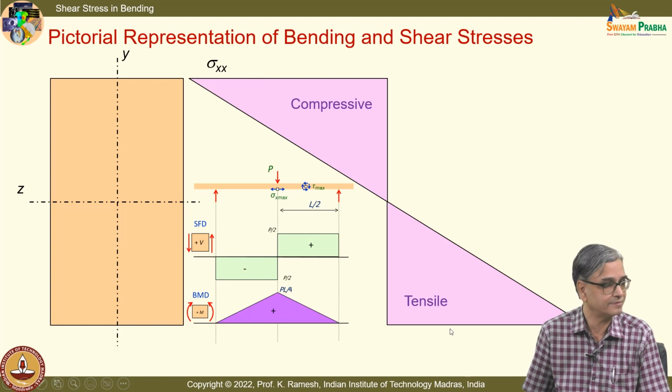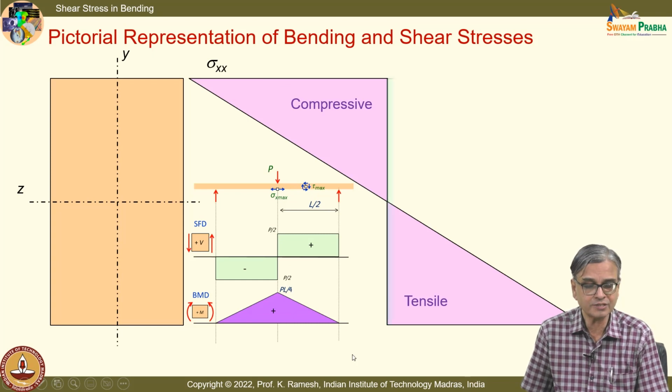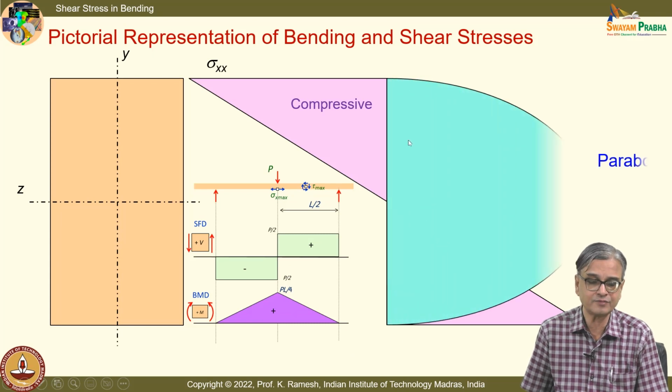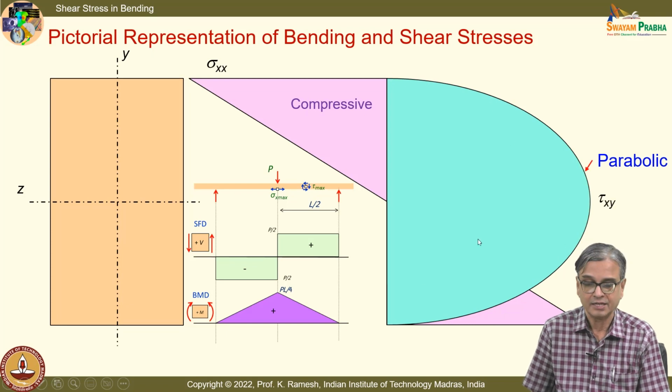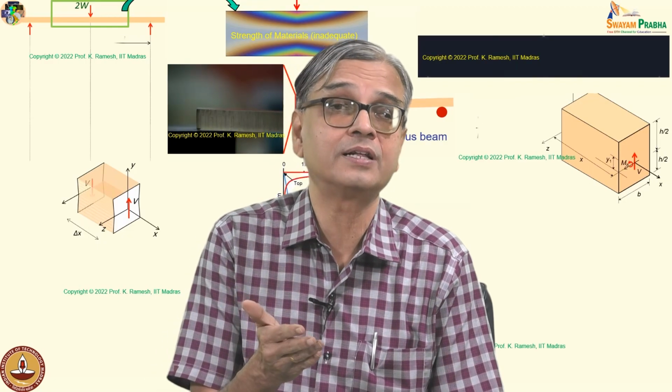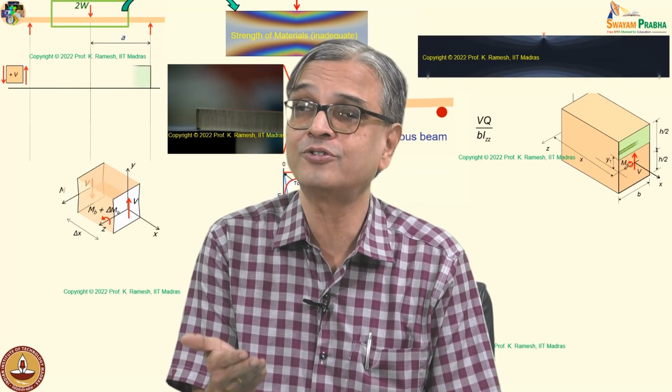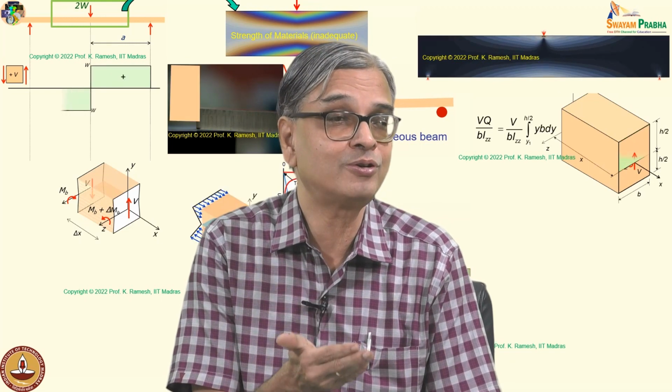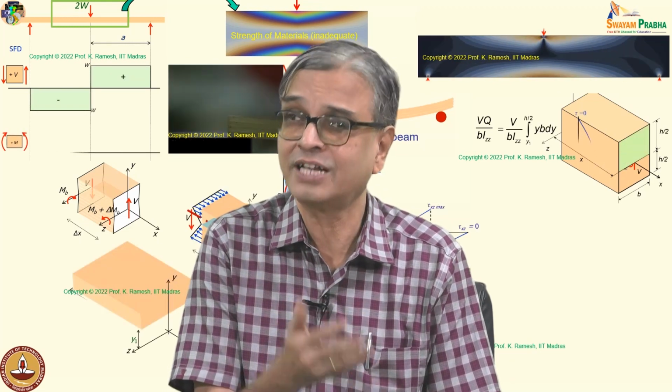Is the idea clear? Many books simply put the shear stress variation. The focus is only on showing that this is a parabola. Fine. And you get duped that shear stress magnitudes are comparable to tensile stress magnitudes. That is what you carry.